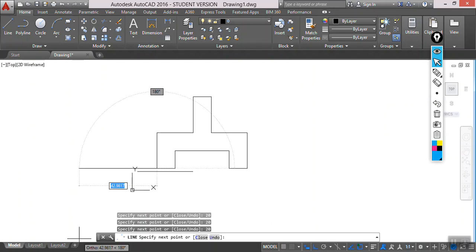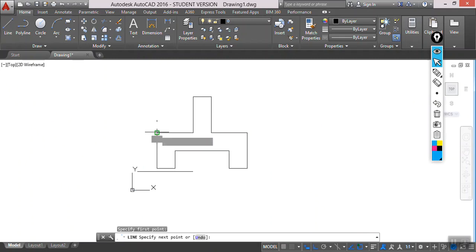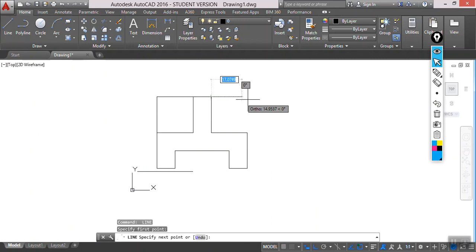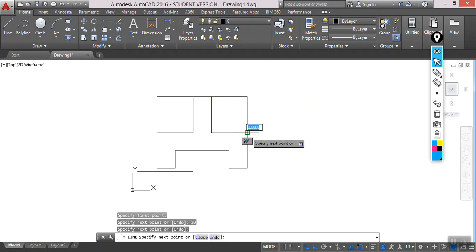By doing this, 90% of my front view is over. Now the block which will be resting at the back, you can see in the front view, and in the same way this side also, a small square of 20 mm will be resting there.